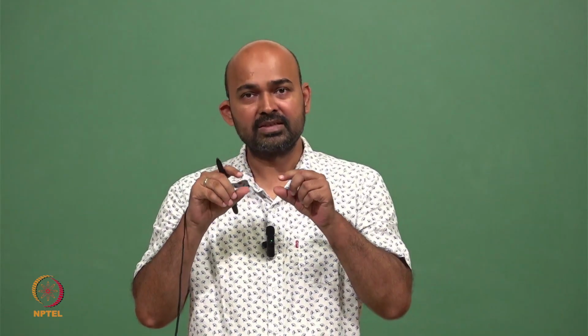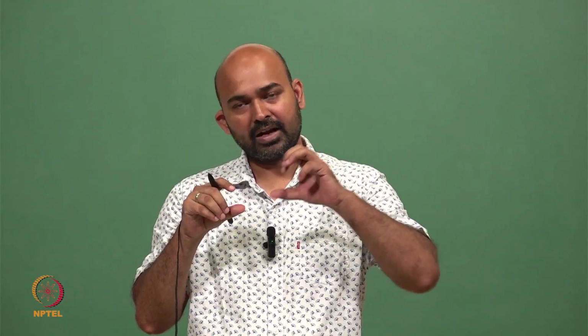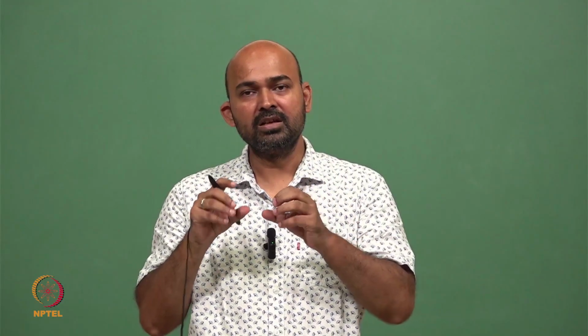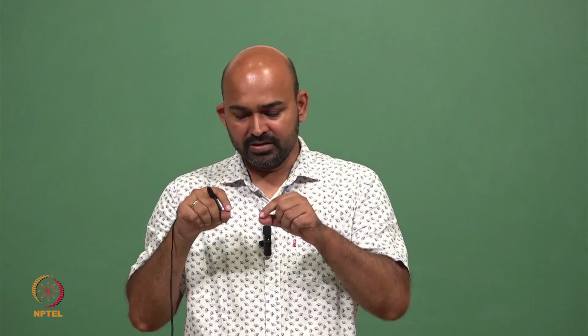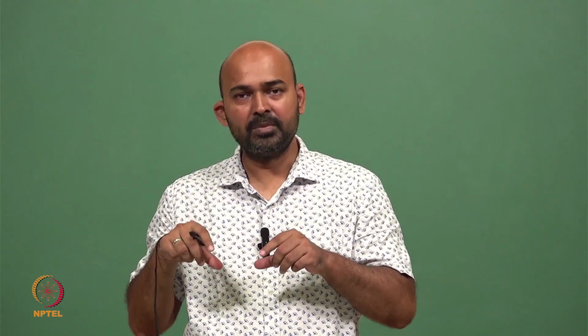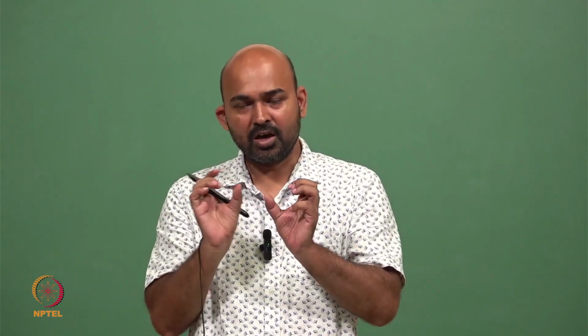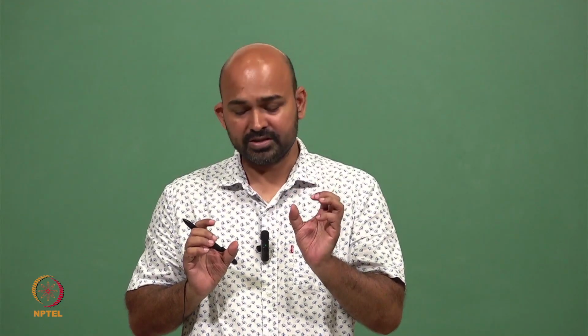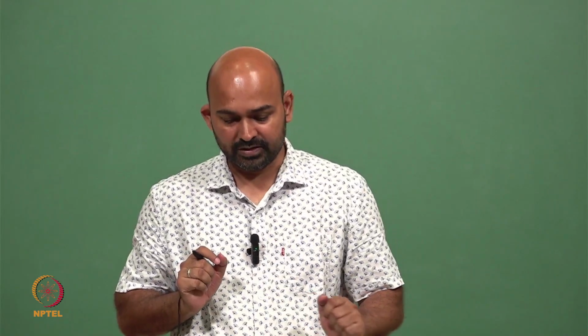So we can use this MOSFET structure as a radiation sensor, where this gate oxide is the primary sensor where we are trapping the charge based on the radiation, and this deep trapping of the charge changes the threshold voltage of the complete MOSFET, and we measure the IV characteristic and measure how much shift there is. This shift is proportional to the amount of radiation received by this MOSFET.